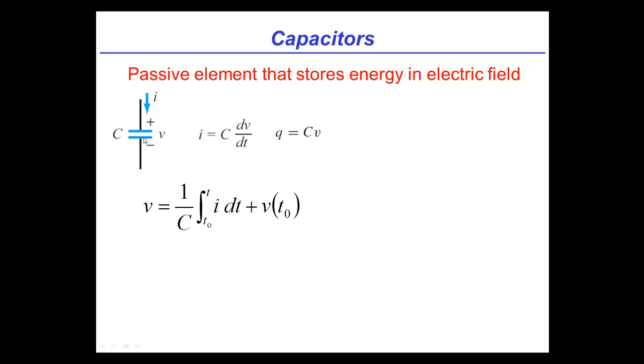That's right, because think about it. What have I got here? I've got two plates which are conductive, but they're separated by an insulator. So as far as DC is concerned, once you ignore that initial charging step, a capacitor looks like an open circuit. Okay, that makes sense to me.